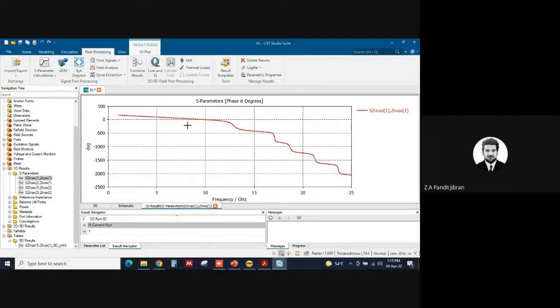So here, what is common? Phase is common. What is different? Here it is patch dimension. There it is the location of the reflector. So you have to map. Phase is common. For example, you want to compensate the phase at X location. For example, 45 degrees you have to compensate. At X location, you have to come back here and find out.